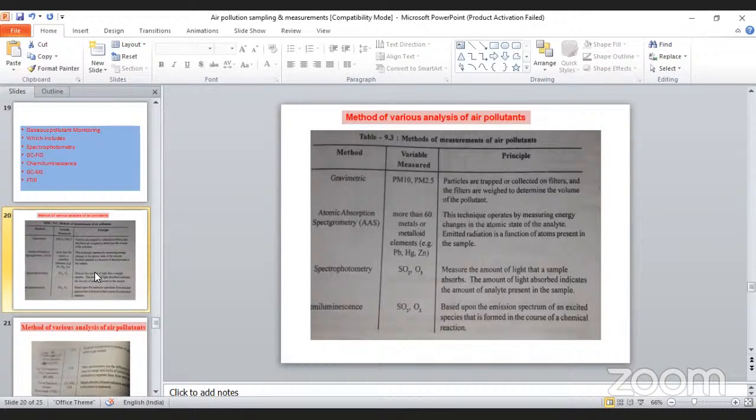Gas chromatography, which uses different types of detector. One of the detectors is the flame ionization detector, which is useful to find out the gaseous components, specifically volatile organic compounds, which respond proportionally to the number of carbon atoms in gases. This is also based on the absorption desorption phenomena, and which indicates based on the number of carbon in the gaseous sample.